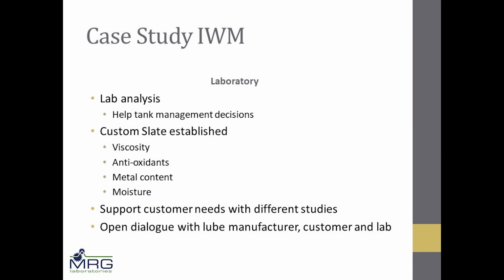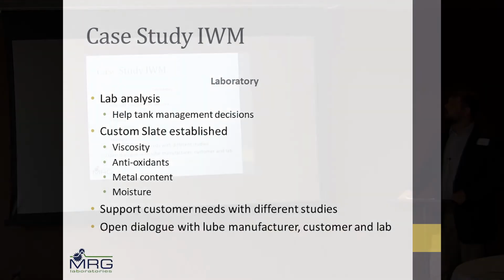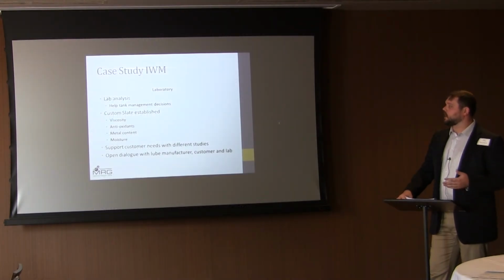All right, so a little bit of case study. So with IWM, like I said, the lab analysis, we had a custom slate that looks at their viscosity, antioxidants, so specifically the phosphate esters, that's the phosphate and the ester that's added into the oil from the manufacturer, the metal content of the oil, and then the moisture of the oil.